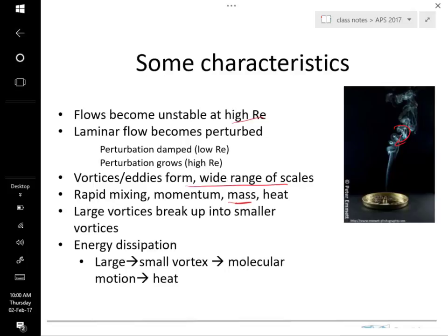They're just using up energy. So the vortices that we've been seeing are going to be an important component of the energy in the flow. And so what we can then think about, I think, is that we've got this system where we've got big vortices and smaller ones and smaller ones. And these guys are consuming energy, and they're doing that over a wide range of scales.